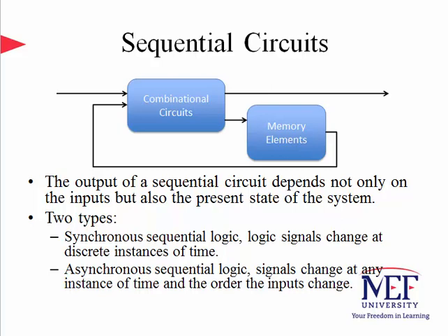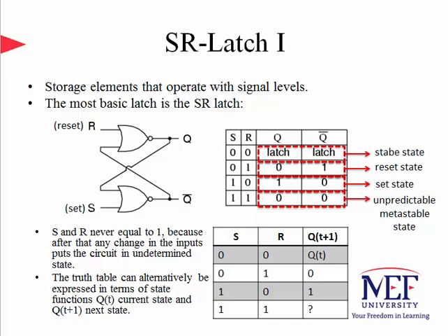Next, we will cover logic circuits with feedback that are the basis for storage elements and memory. A storage element can maintain a binary state indefinitely until changed by an input signal that is external to the circuit, and then it switches the state of the circuit. The most basic storage element is known as the SR-Latch, where S stands for set, and R stands for reset. The SR-Latch can be manufactured using two NOR gates, as shown, and the truth table for this circuit is given to the right of the logic diagram.